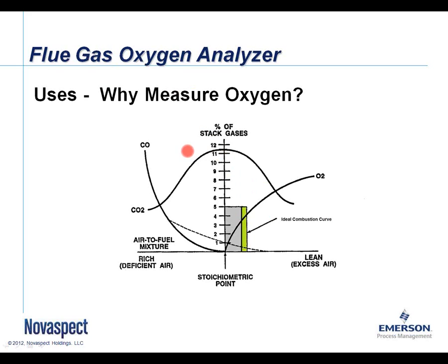blocking a filter. Adding an actual flue gas measurement allows us to set up a control strategy where we can capture some of that efficiency and move back down closer to the stoichiometric point. And by the stoichiometric point, we're talking about the point where all the fuel is being completely combusted and there's no unburnt carbon chains left in your flue gas stream.